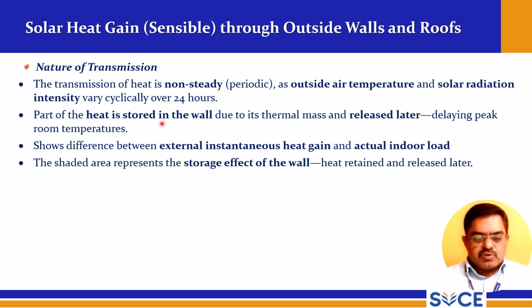Part of the heat is stored in the wall due to its thermal mass and released later, delaying peak room temperatures. This shows the difference between external instantaneous heat gain and actual indoor load. The shaded area represents the storage effect of the wall, heat retained and released later.